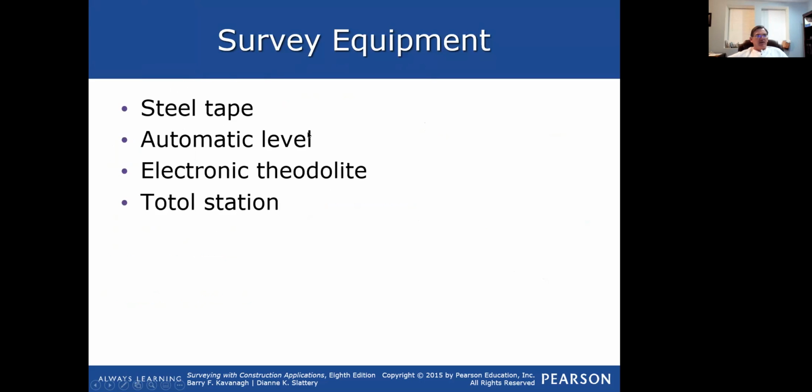This is some introductory surveying equipment. We're going to talk about some more later on, and I'll show you some demonstrations. The main thing for you to understand is surveyors utilize a total station, which is spelled wrong at the bottom of the slide. Total station is the number one thing that's utilized by surveyors today, as well as construction surveying and construction managers who want to check something. But a theodolite and a steel tape can be useful. Theodolites only turn angles and not distances, so most people wouldn't have one of those anymore.